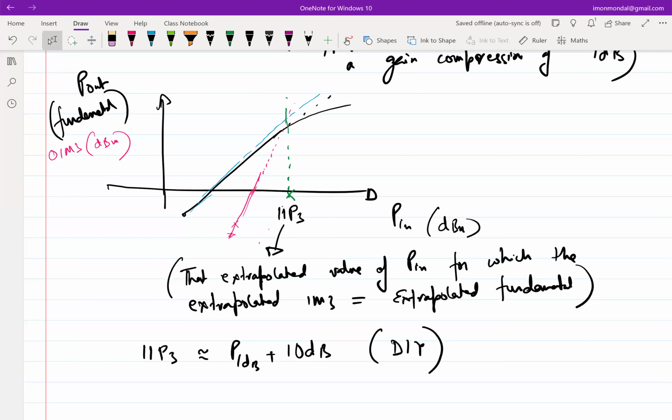But having said that, there is an issue: normally antennas are single-ended. When antennas are single-ended, the LNA attached to it is also single-ended. So in the case of an LNA, you need not always neglect the second harmonic term. Just like you have P1dB and IIP3, the second harmonic will give rise to IIP2, right? But that is not part of the discussion right now, so I will leave it out. If you are interested, you can look it up.